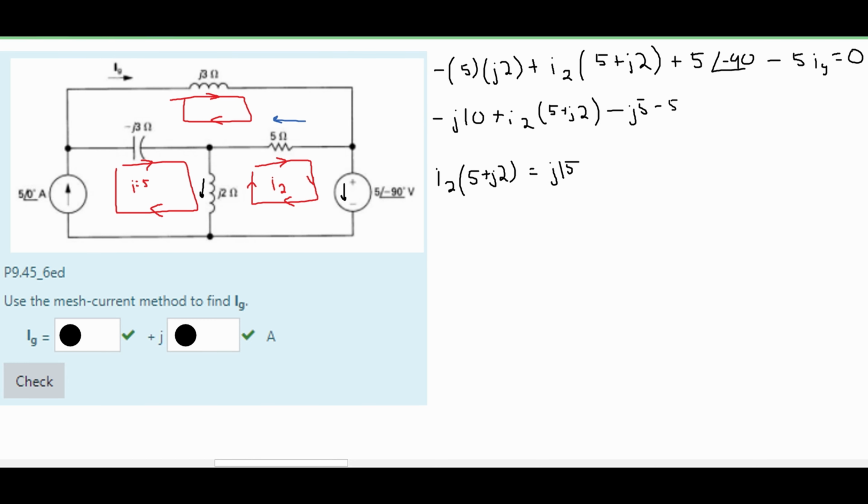And then we're going to have the same thing down here, set equal to 0. And if we move this over with this constant, we will have a plus 5 times our I of G. Remember that IG is what we want to find. Now we need to write an equation for our I2 so that we can plug it in. Well, the last thing that we can do is look at the current flowing through here. We can see that we have this first current right here going in the opposite direction over the negative 3 ohm resistor. So we will have a minus our 5, because that's the current, times our impedance, which is negative J times 3. And then we will have our minus, because we have this second current, that's over the 5 ohm resistor. So we're going to have 5 times our I2. And lastly, we're going to add our I of G.